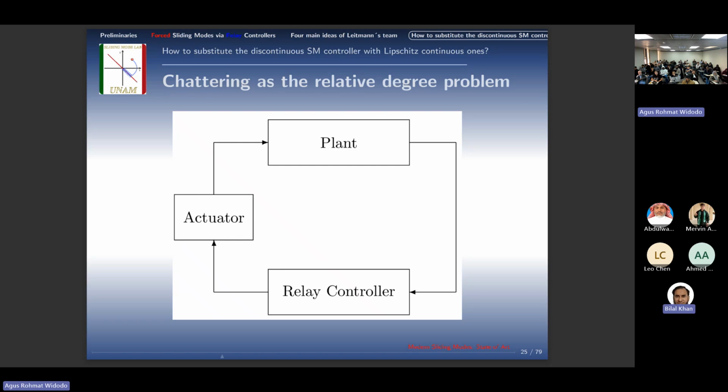So what have we understood? We understood a very simple story. If we do theoretically ideal control, it will work perfectly. But there is one policeman. The policeman is the actuator. If here the relative degree is 1, here the relative degree will be more than 1, at least 2. So what do we need to do here? We need to ensure the same motion, even if there is some extra dynamics. That is why we need to converge not only to the signal, the variable we need to follow, but also at least for one of its derivatives.